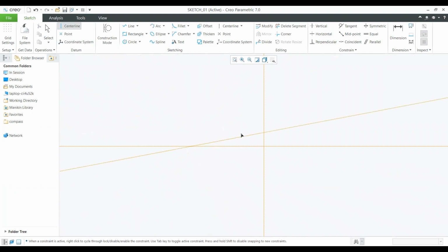We can create it at any angle. We can create perpendicular, vertical, anything. Now see, when I select this line as vertical, we have a small symbol here. Okay, this is the straight line symbol. Again, if I move it to horizontal, it shows me the horizontal symbol. So what is that symbol? This symbol basically represents the constraints. So let's go and see that.